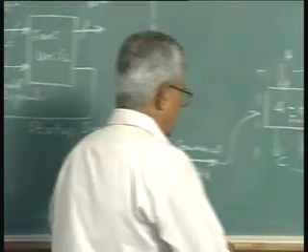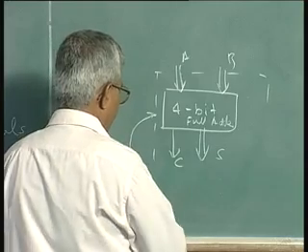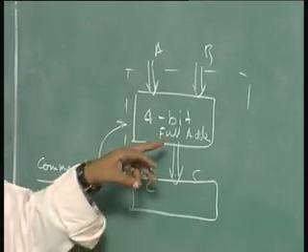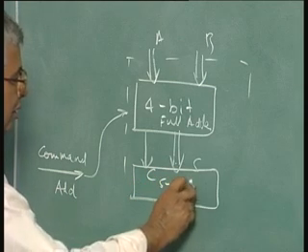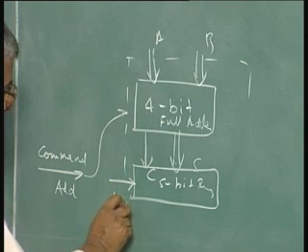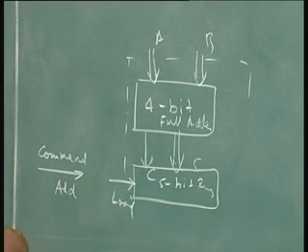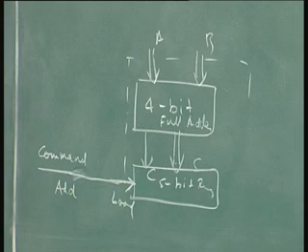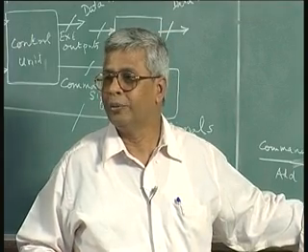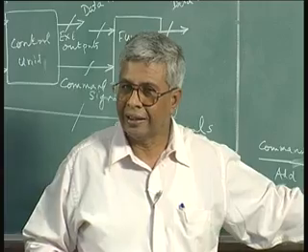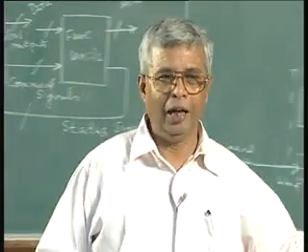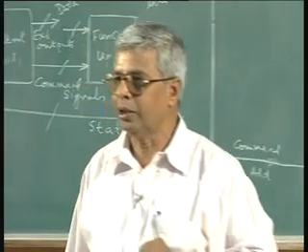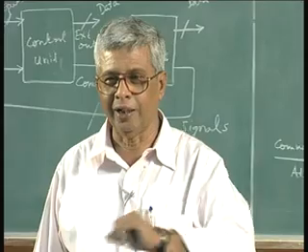So, what I do is, as a simple solution, I put a register. After all, the adder output can go into a register. How many bits? 5 bits, because this is 4 plus 1, 5 bits. So, you get a 5 bit register, and the register will have a load signal, and I will give this command into this load signal. So, even though I am having an illusion of controlling the adding, I am not controlling the adding, I am controlling the loading of the adding. The result is available at my request, at my command. At the controller's command, the adder result is available. Adding must have happened earlier, but I am not going to use it. I will look at it, okay, you do what you want, but I will look at you only when I am free. That is what the controller says to the full adder. They do not speak anyway.